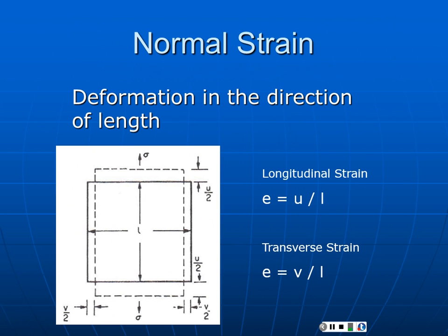Now, when we apply axial strain, when we apply a stress in a direction, you're going to see the body will stretch in that direction, or if it's compressive, then it'll shrink, and you're going to have a lateral response. And so any component that you work with will shrink laterally when you load in tension, and it will expand laterally when you load in compression. You're familiar with this as a kid in your high chair. You played with squishing food and watching this stuff happen.